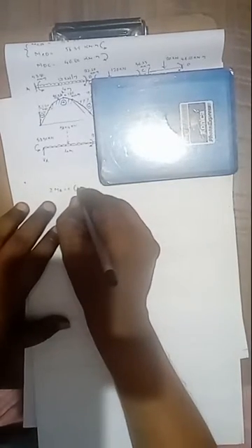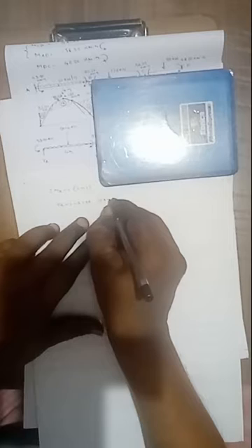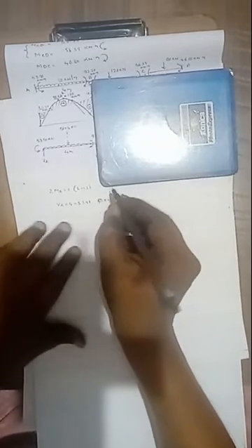Here only this portion we have to consider, that is only the LHS. In this LHS, by taking moments of all the forces about B equals 0, VA into 4 is clockwise, that is positive. Then there is a support moment, which is anti-clockwise, that is minus 53.90 kilonewton meter, and this span is subjected to a UDL of 50 kilonewton per meter. Then the total load is 50 into 4, which acts at a distance of 2 meter from either end.